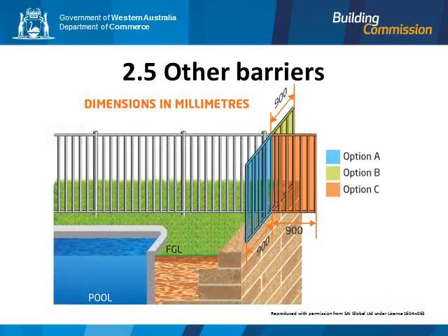A new addition to the standard is how to deal with the intersection of a pool barrier with a retaining wall. If you look at figure 210D of the standard, this should be on page 23, you will see a diagram for this. Where intersections of a barrier and retaining wall occur, the barrier must extend 900 mm as an overhang or return at the edge of the retaining wall. Where a 900 mm return is used, it must be flush with the face of the retaining wall. However, there is no requirement to panel over the fence to remove the gaps.